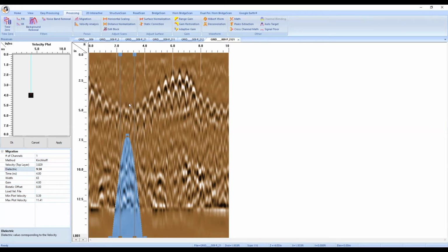It gets much deeper and then much shallower over a very short 6-foot distance. Usually rebar remains fairly consistent in its depth over large areas. Wire mesh generally changes its depth dramatically over a small period of time. But this is actually where one wire mesh ends and another mesh is beginning. So we're seeing two overlap one another here.